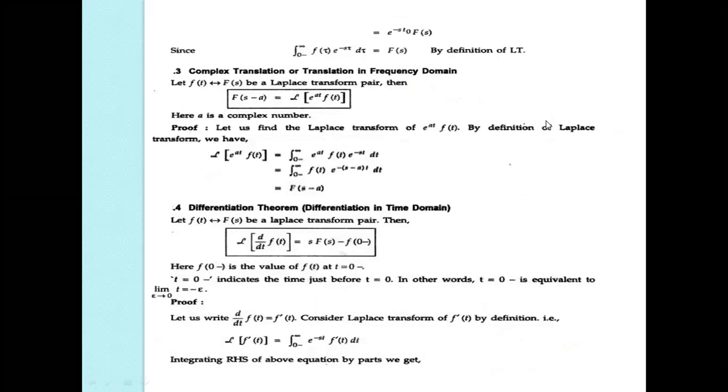Now, you see here they have the Laplace transformation of f of t minus t naught. Don't write it as a 0 minus, students. It's bilateral only, don't write it as unilateral. Bilateral, minus infinity to infinity. So it is e power minus s into t naught into F of s. Got it?